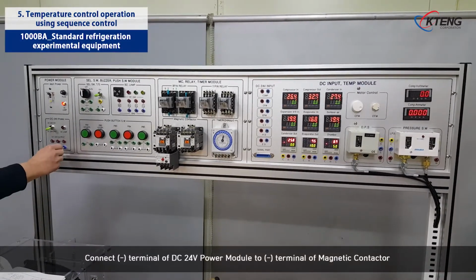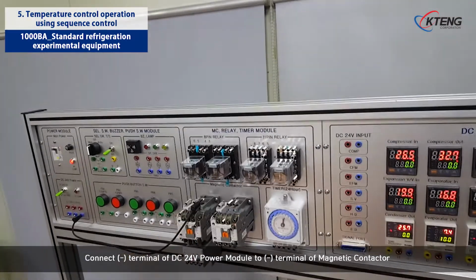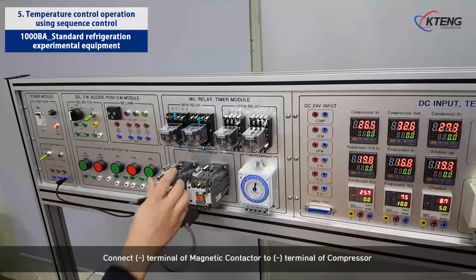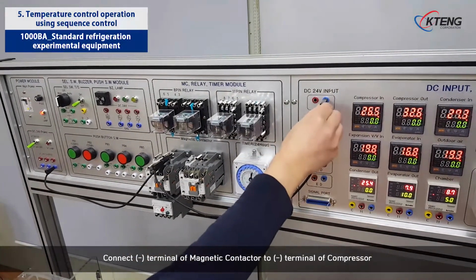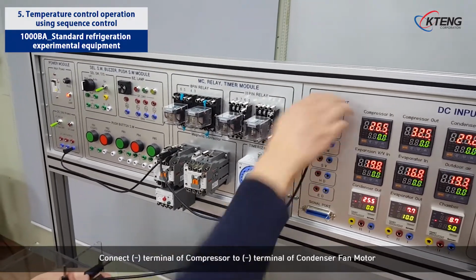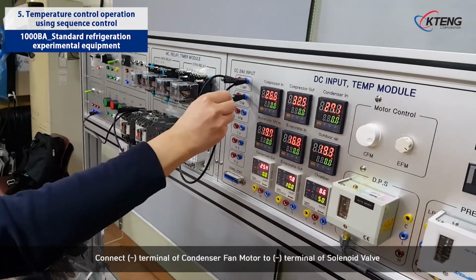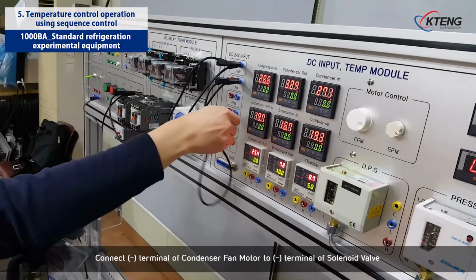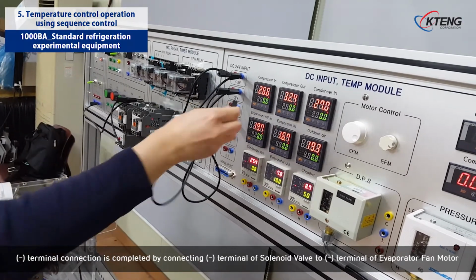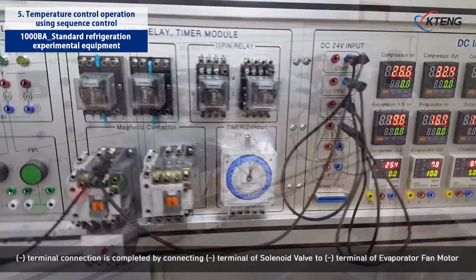Connect negative terminal of DC 24-volt power module to negative terminal of magnetic contactor. Connect negative terminal of magnetic contactor to negative terminal of compressor. Connect negative terminal of compressor to negative terminal of condenser fan motor. Connect negative terminal of condenser fan motor to negative terminal of solenoid valve. Negative terminal connection is completed by connecting negative terminal of solenoid valve to negative terminal of evaporator fan motor.